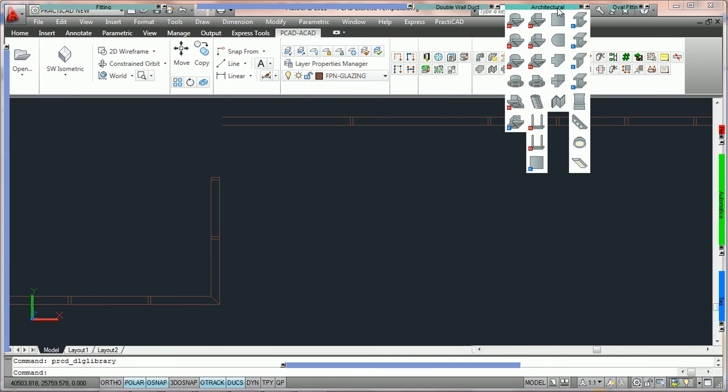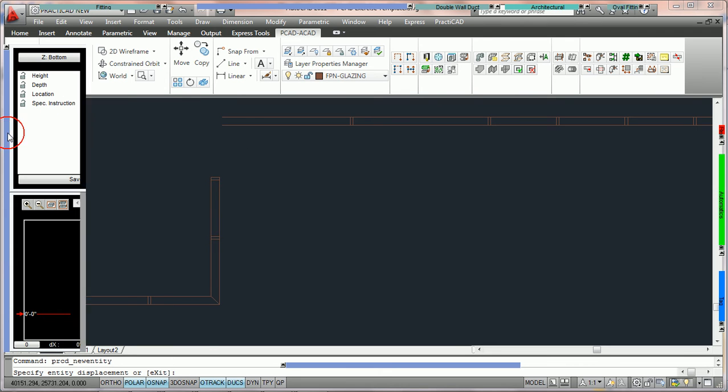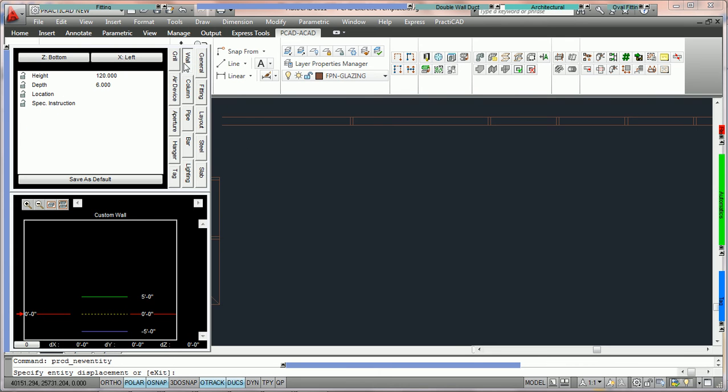What we need to do is go into the bin and pick out the custom wall. Going to click once. We're then going to come over to the left to the item box. You'll notice that the wall tab should already be depressed. We're going to choose to hold this wall by the bottom left. So toggle through your combo box and choose bottom left corner point.